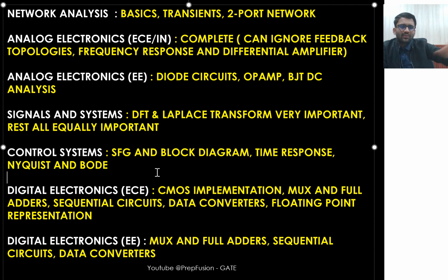But just at surface level you need to know, like if someone asks you for the resonance frequency, you should know how to find it: we put the imaginary part of impedance equal to 0. And you also need to know how to determine complex power. So you should know the basic things. But in AC, you do not need to get too deep, I am spending so much time on AC. So that's about network analysis.